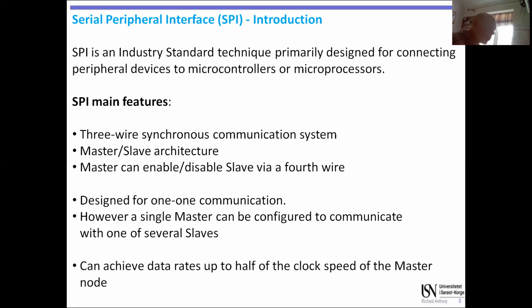Okay, microcontroller to microcontroller or microcontroller to peripheral device. It's a 3-wire synchronous system. It's got a master-slave architecture, which means one end is controlling and the other end is just following the rules, if you like. One end is configuring and controlling the clock in particular. Okay. It's designed for one-to-one communication.